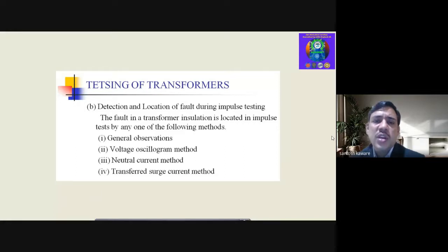So it may sometimes be a manufacturing defect, but other supporting things can also affect our design. Then we added some passivator into that oil, and since then there has been no failure of such converter transformers. So these minute defects may remain in our design. For that, such testings are used.